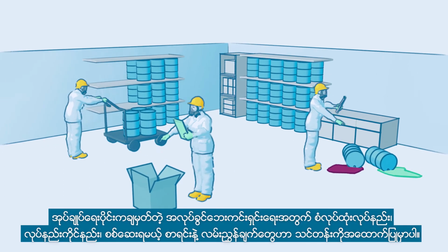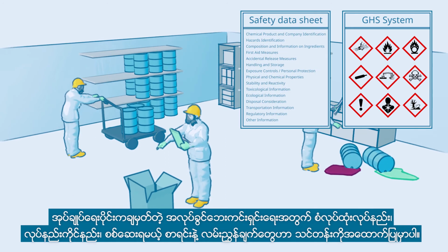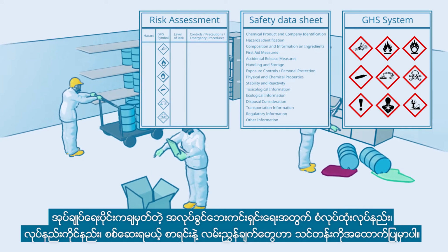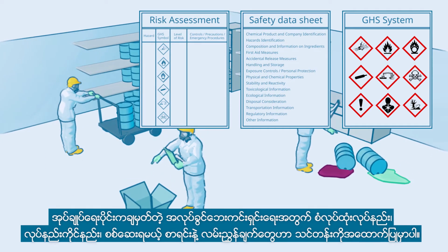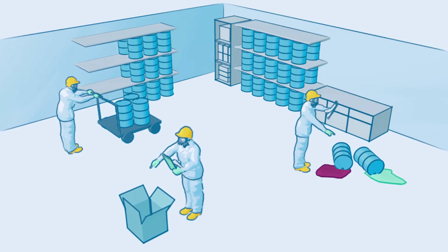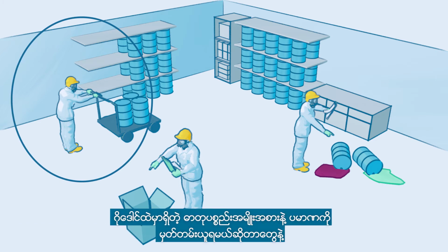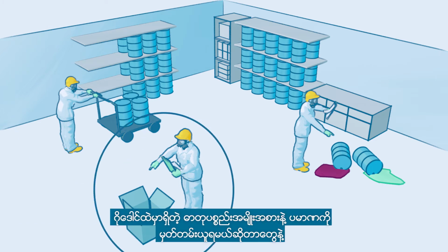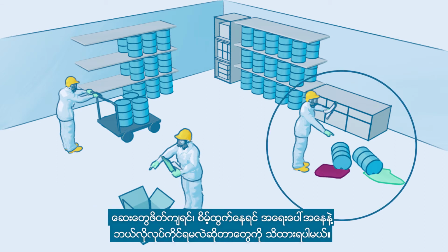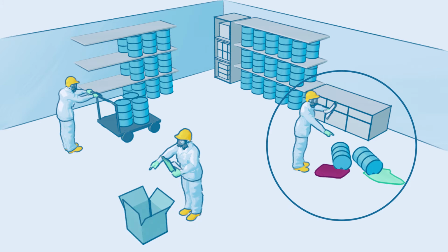Standard operating procedures, work instructions, checklists, and guidance by the management on safe work practices will help to reinforce the training lessons. For example, how workers should safely handle and store chemicals, maintain updated inventory records on types and amounts of chemicals being stored, and respond to emergencies such as a leak or spillage.